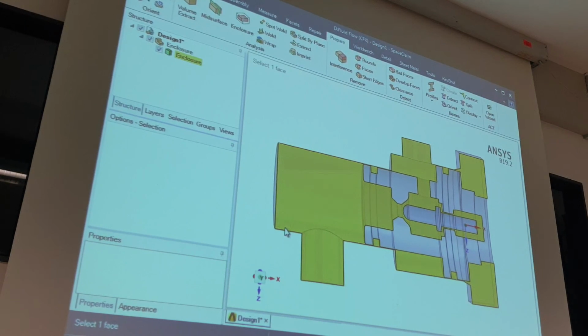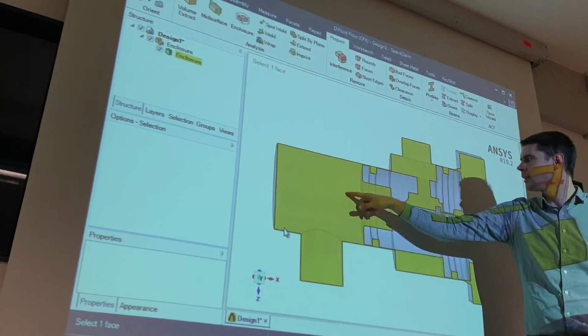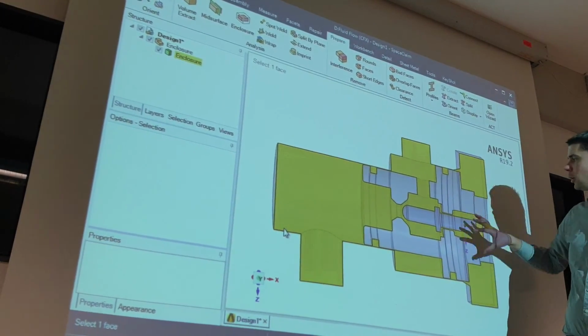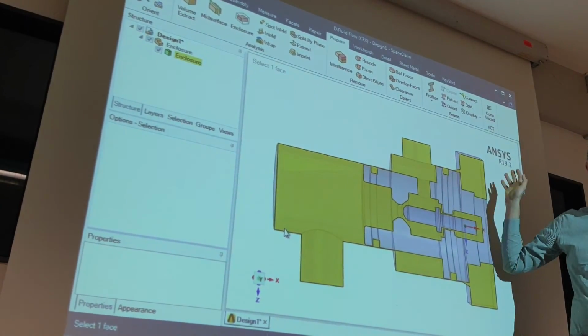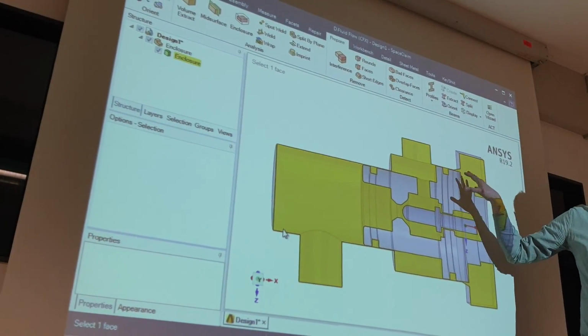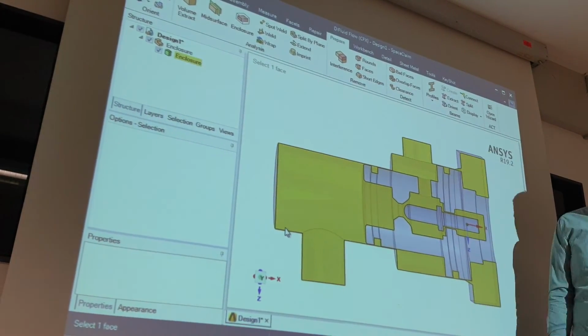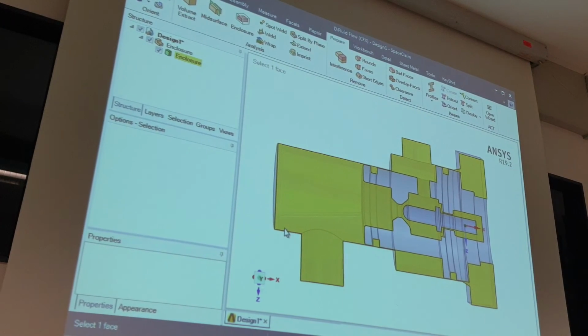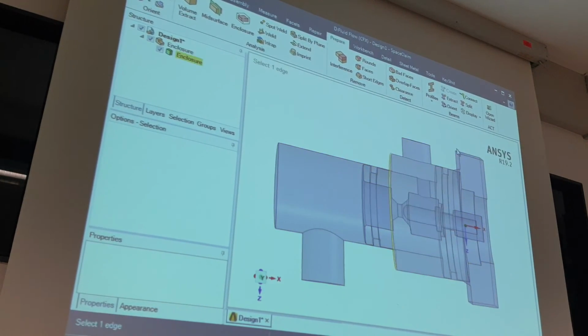Okay, and now I have also small gaps. Of course you don't need all these small gaps. Yes, small gaps is no flow. So your flow comes in here, goes outside here, and here you don't have velocity, nothing. Yes, it's a stay flow. It's nothing here. Yes, you can delete it without thinking. All small gaps, you have to delete.